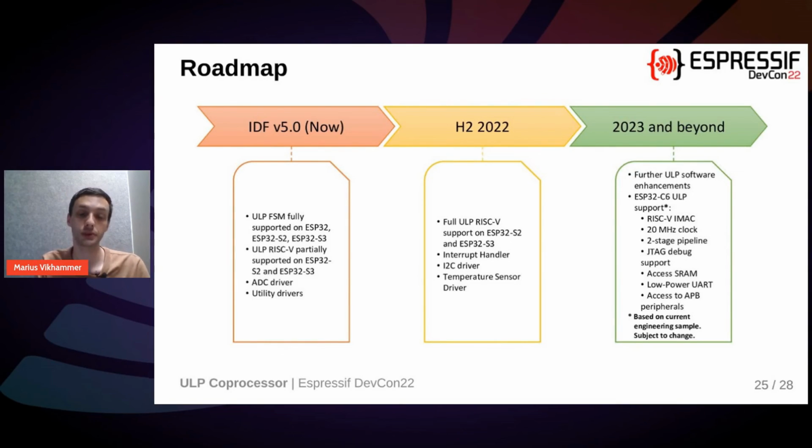And for the near future, aka the upcoming half a year, our goal is to keep on expanding this support. We want to aim for a full support for the ULP RISC-V on both S2, S3, all features, which includes interrupt handlers, I2C driver, and the temperature sensor driver.